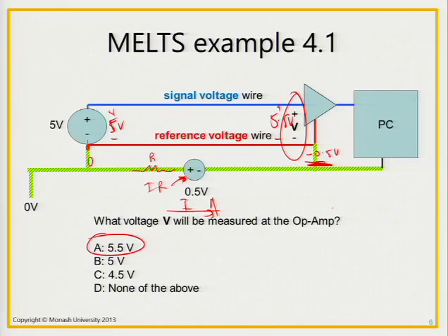Okay, so how can we fix this? Yep, question? Why is current going from left to right? Could be going from left to right, could be going from right to left, whichever way. It's just that I've just written a current here. In fact, it would be a sum of many currents. Whatever uses this as an earth wire, there's lots of currents coming into it. So it's not just here. You might have some big device connected here, and that might use this as an earth as well.